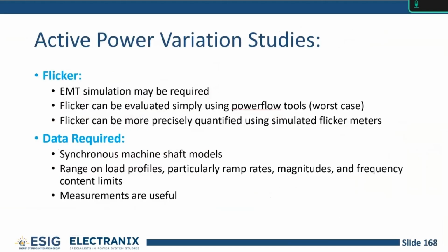that the flicker standards are a little bit out of date, or at least are based on older incandescent technology, where a certain change in voltage will cause a certain change in perceptible light in incandescent lights. And if you get to a certain frequency and a certain variation of voltage, it will start to be annoying.